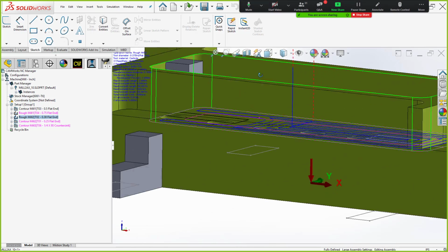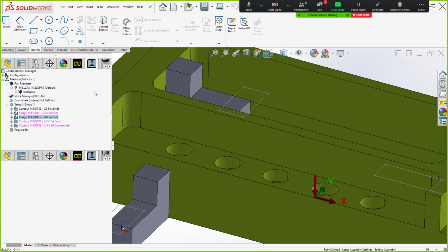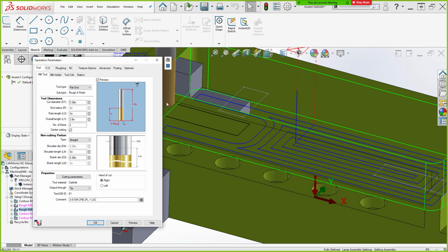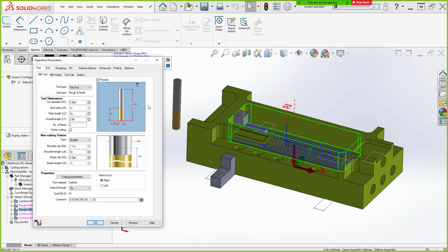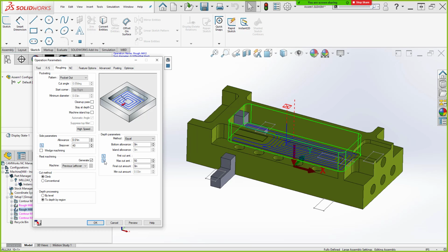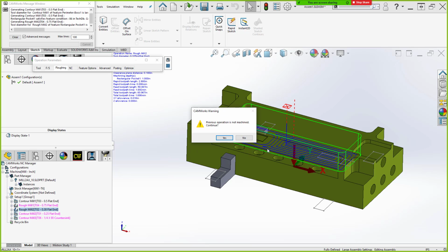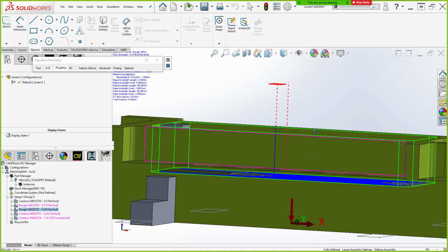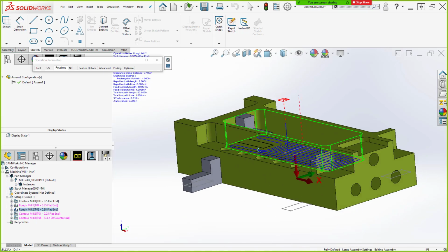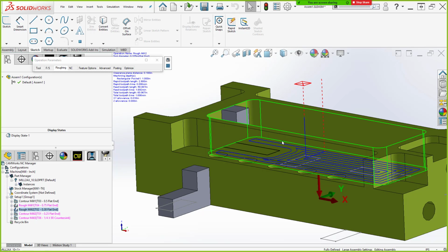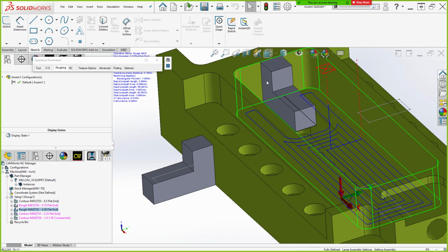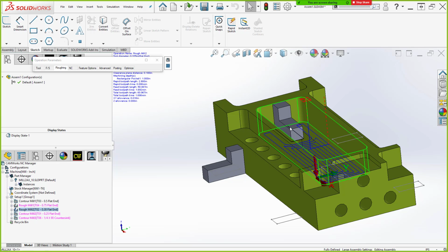So you can see that it essentially does it as a, well, let me double check my heights here. Can you change the lead in, lead outs only for the avoid areas? Yes, you do have some control there. I'll go back to that in a moment. That's a good thing to discuss. Depth of cut here. Let's make sure we're not going too deep. Right, so you can see though, it is getting my point across. I just wanted it to be a little bit clear with a few depths of cut, but essentially what's happening here is we're getting a pure XY avoid on this clamp, right? It doesn't care if it has multiple shelves or heights. It just does a pure XY avoid around it.